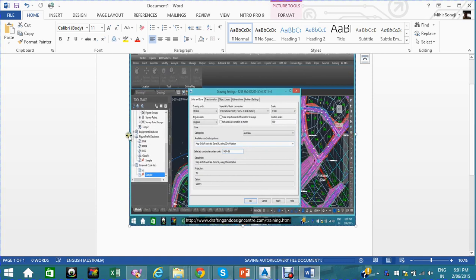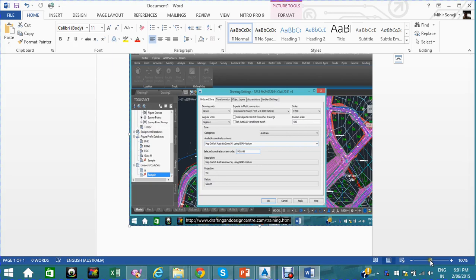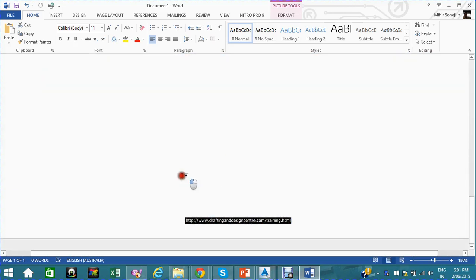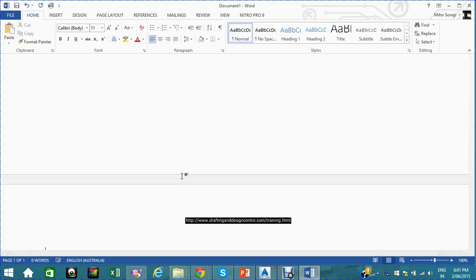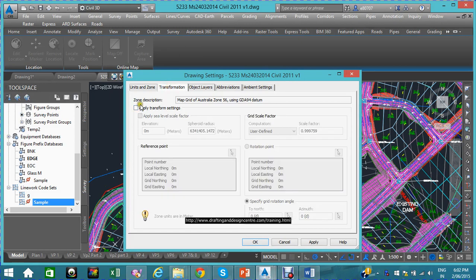And then transformation, there is no transformation. One should not apply any transformation. This is my advice. If the project is more than 2 kilometers in size, you may think of applying it, but just consult your hiring manager before applying a transformation.